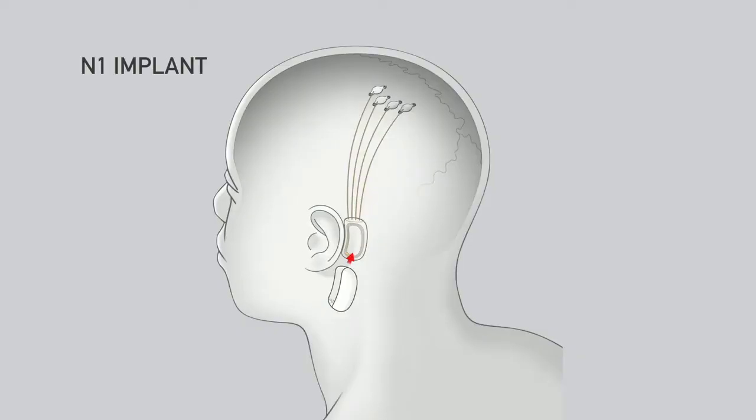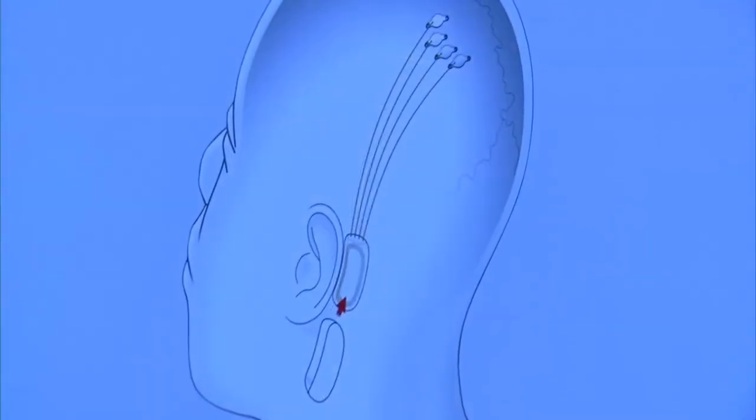And so the N1 implant, we can place, as Elon mentioned, many of these, possibly up to 10 in one hemisphere. For our first patients, we're looking at four sensors, 3 in motor areas and 1 in a somatosensory area, which are connected via very small wires tunneled under the scalp to an inductive coil behind the ear. That connects wirelessly through the skin to a wearable device that we call the Link, which contains a Bluetooth radio and a battery. Importantly, this is the only battery and radio in the implant. So if you take this off, the implant shuts off. And if there are software upgrades or security issues, it's much easier to upgrade the firmware on the Link than it is to try and change the implant.